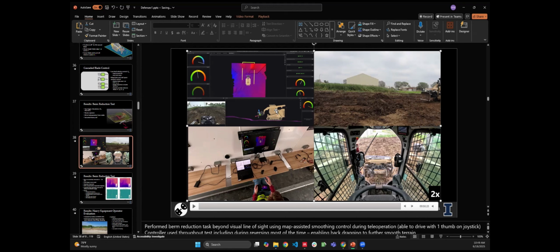And we had some advice from one of the other people in the lab that had done some of this work and said that that was important for doing good CAN communications and avoiding dropped packets and that kind of thing. So that was one of the main reasons that we did it. I don't know that it's entirely necessary, but we had stable performance of the system.